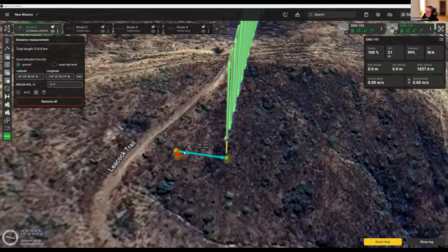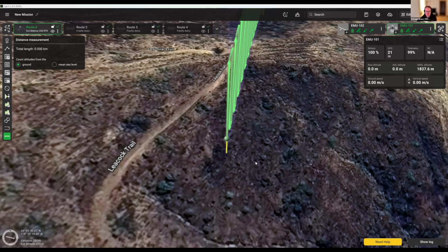That's a good distance for vertical inspections. Sometimes you want to get a bit closer, but with a good camera, it's usually better to be a bit further away to ensure that the flight is safer and that, for instance, when scanning really tall buildings, the drone won't lose GPS if it gets too close.